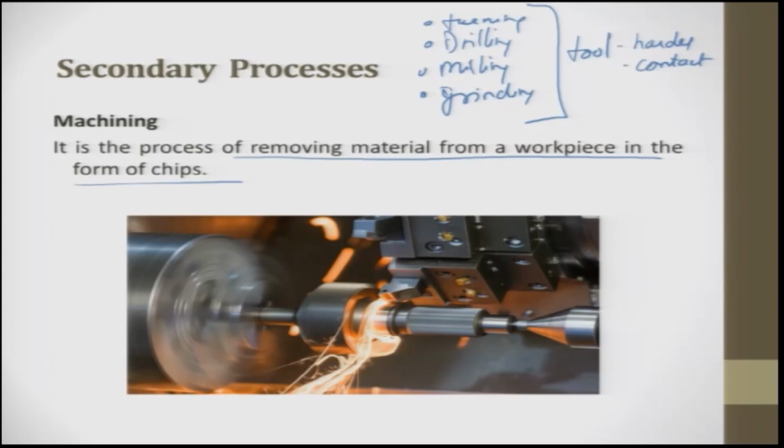A typical example is this, because when it is in contact there is going to be friction. So, tool and workpiece, you will have friction. This friction increases the temperature and you try to produce a chip. So, the temperature tries to dictate the material, and the temperature has to negotiate.